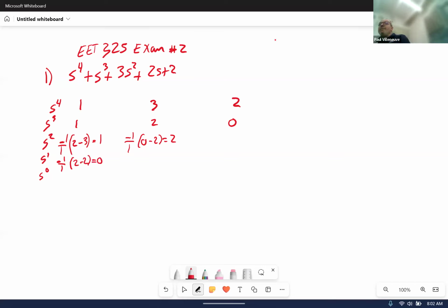Now, some of you made mistakes of substituting epsilon at this point. You cannot substitute epsilon at this point because you have to check and see what that next number in that row is going to be equal to. If that is equal to 0, then you can't use that little epsilon approach. You have to use the auxiliary equation. So let's go ahead and do our next step.